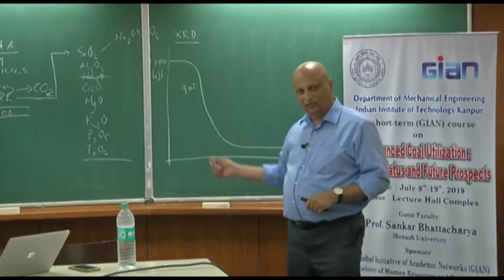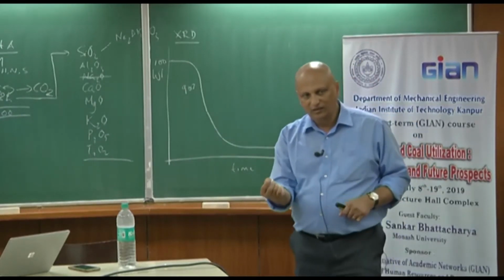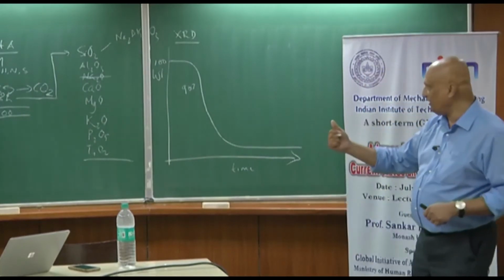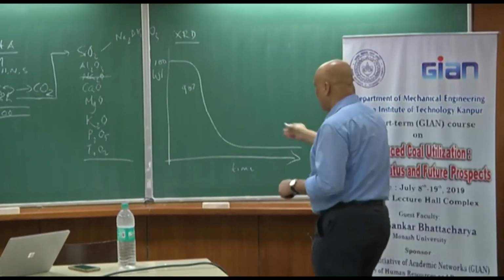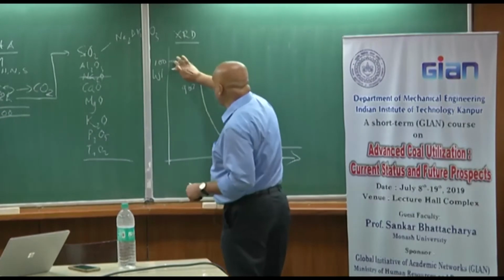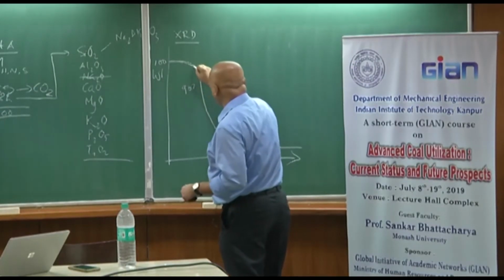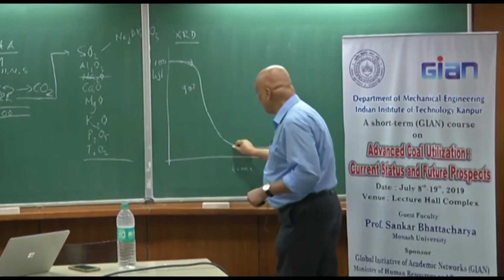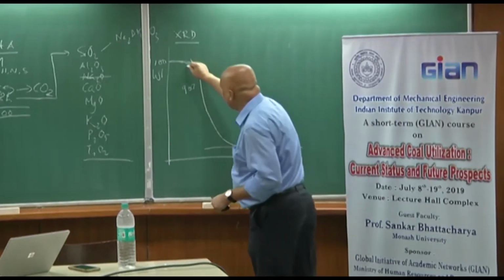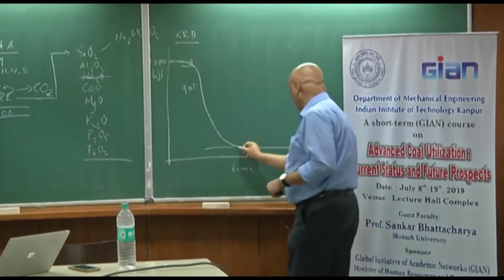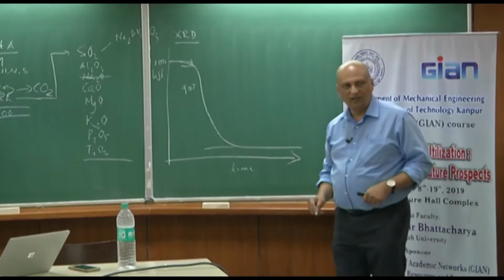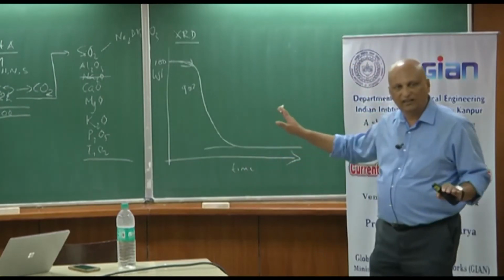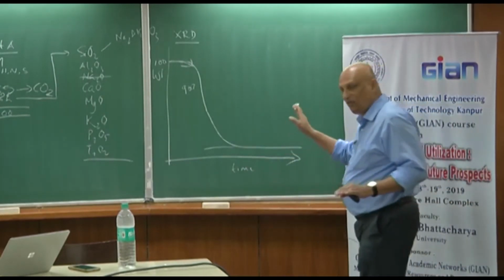What this means is, if you take a certain amount of coal, subjected it to a temperature of 900 degrees, you will see this type of curve, that it first loses its moisture here, and then it loses its volatiles between this point and that point, and then its weight stabilizes, and it doesn't lose any more at that particular temperature.